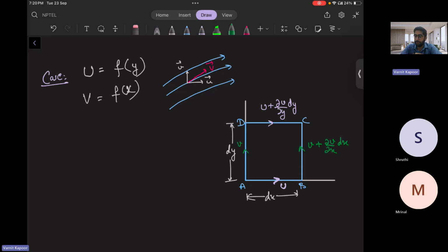All right, so this generally represents rotation. These components represent rotation of velocity u and v in the y and x directions. So rotation of velocity u in the y direction is this. Rotation of velocity v in the x direction is this. Okay, so that means if there is a difference in the velocity, the fluid element is going to move. So fluid itself is something that is called continuously deforming, as we defined in the first tutorial, the difference between solid and fluid.